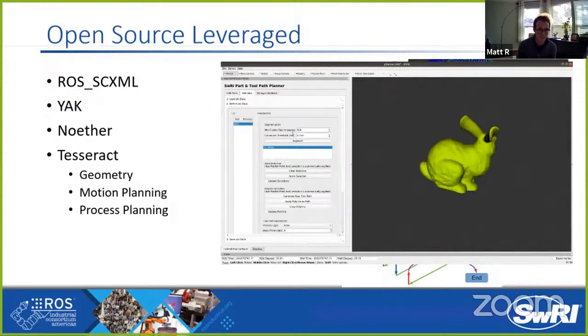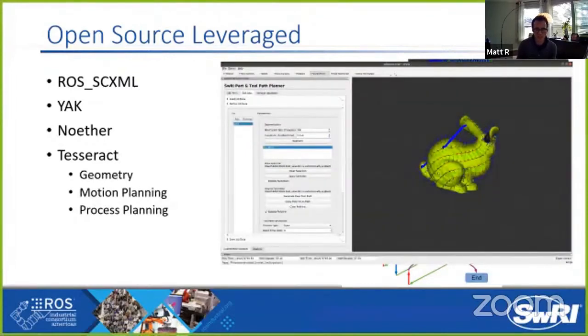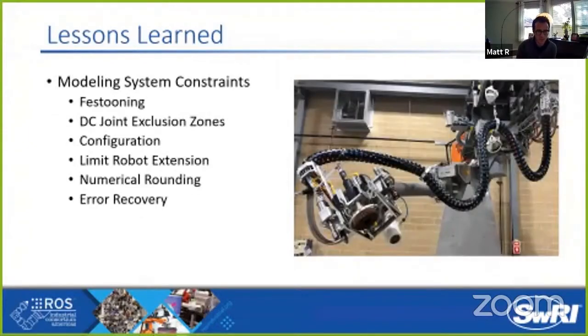And the idea here is that we want evenly spaced rasters across arbitrarily contoured surfaces. And so this applies a heat method approach, right? So in thermal, if we apply the laws of thermodynamics, if I apply a heat source, the isotherms are evenly spaced, and that's what you get here over arbitrarily complex contours. And this is a really nice enabler for when we want to do painting or precision polishing and sanding applications. So we're excited to offer this up to the industrial community.